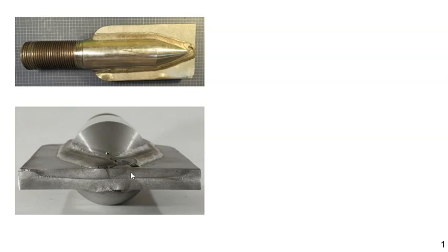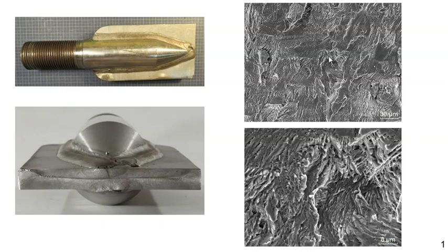You'll notice that the fracture is relatively flat and that there's no plastic deformation of the metal. And these are indications of the failure mode for this fracture. This area was then cut out and examined with a scanning electron microscope. And the scanning electron microscope images are shown here. This is a lower magnification image and a higher magnification image.